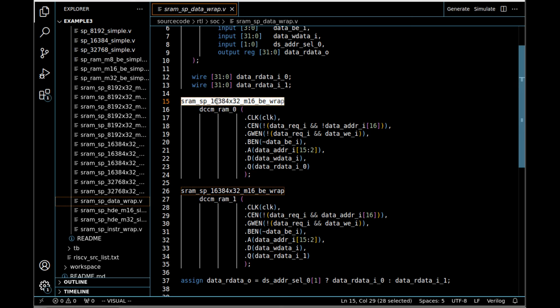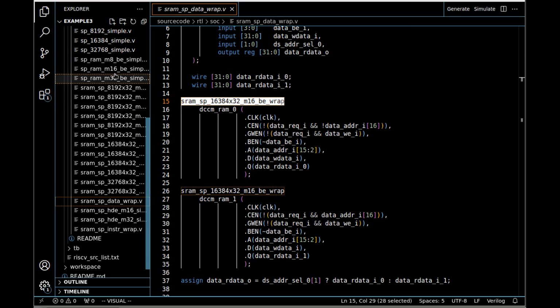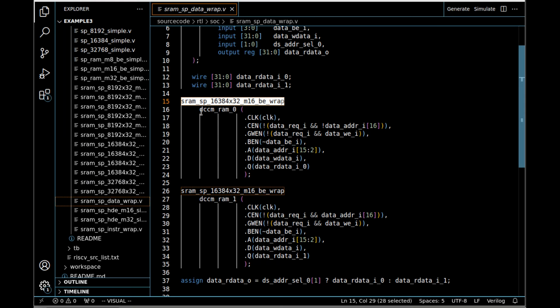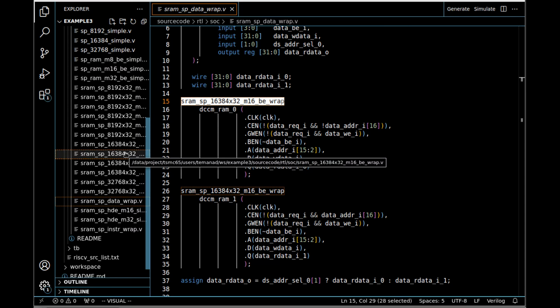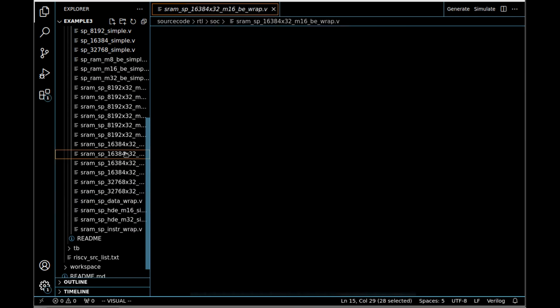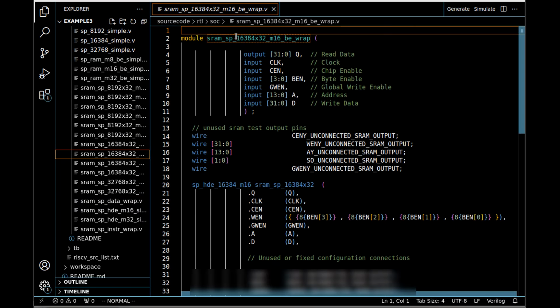So then I would go and look for, we've prepared several of these types. If I just take one of them, like a 16384 by 32, and it doesn't really matter which one exactly, this is the MUX 16 one. So this is actually, I think, the proper one that we had over there. So here I'm going to do the actual connection to the SRAM that I compiled already. So inside this, I'm going to get that simple interface that's kind of generic for any SRAM,